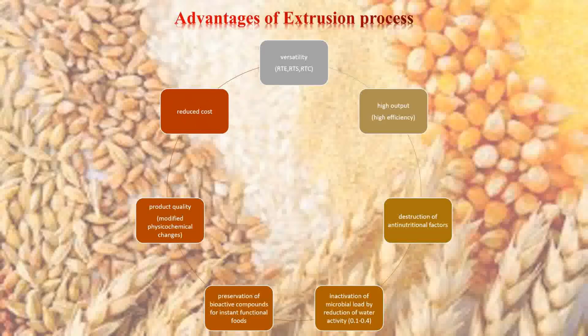So the cost of unit operation in case of twin screw extruder is a little bit less compared to the single screw extruder, whereas in case of single screw extruder, in one batch operation or one batch setup, it has to be recycled quite a number of times in order to have that final desired product that meets the total quality dimensions.